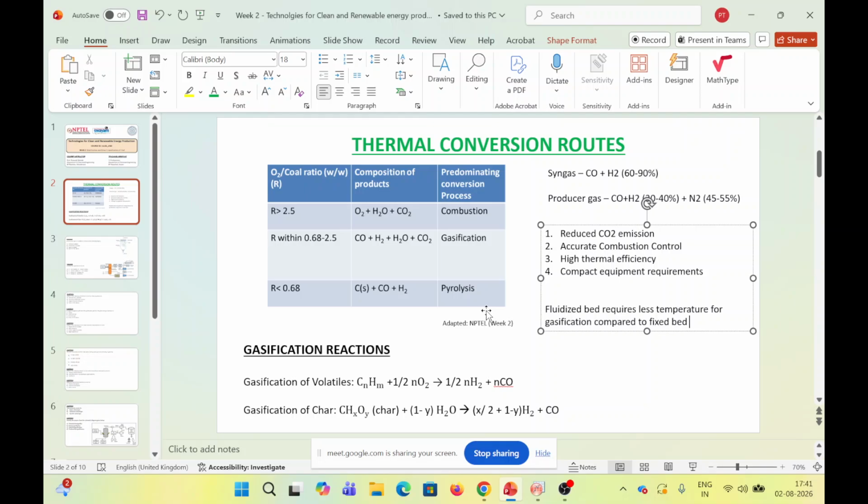So how are you going to do that lowering of the energy or cooling of the syngas? Through two ways. One is using a quenching technique, and another one is using a boiler method. In the boiler method, you get a raw hot syngas, and then you make that syngas enter inside a high pressure steam boiler. Once the syngas enters the boiler, it expands and transfers its energy to the steam, and then the steam rotates the steam turbine, and the electrical energy is extracted.